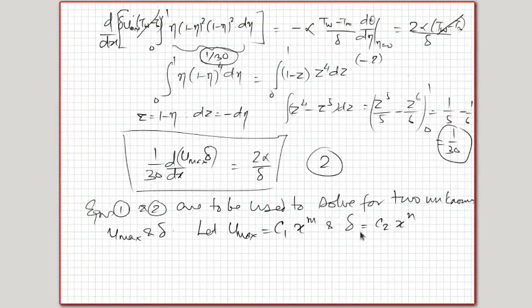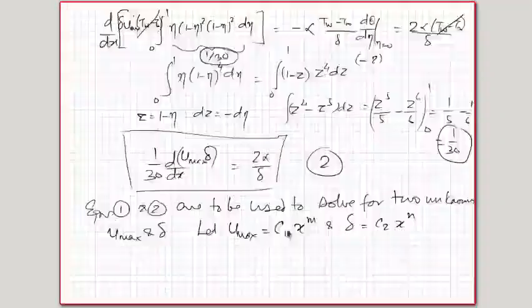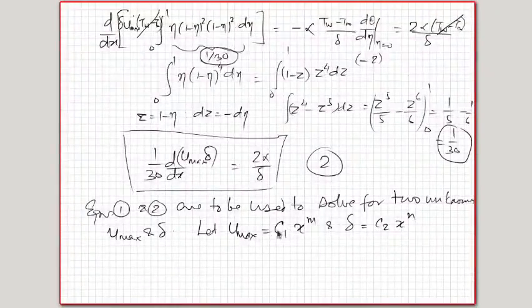You know that delta by x goes as Ra_x to the power of minus 1 by 4, and similarly U max into H by x by alpha goes as Ra to the power of half. So this is something that we already know. So automatically the powers are determined from there, but we will still determine them from this analysis itself.